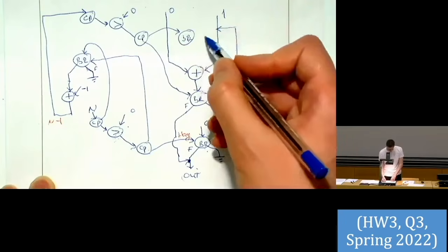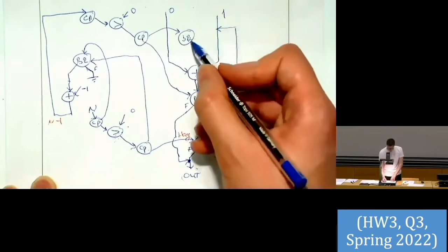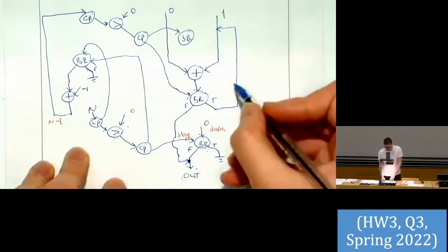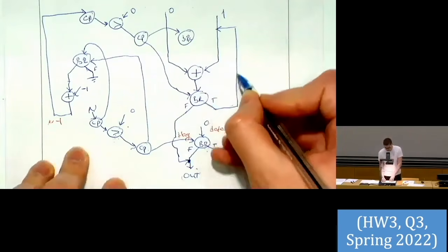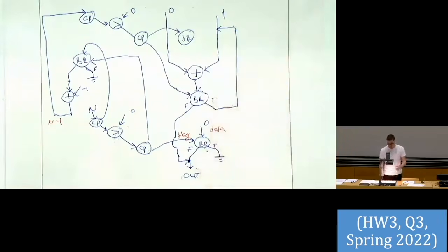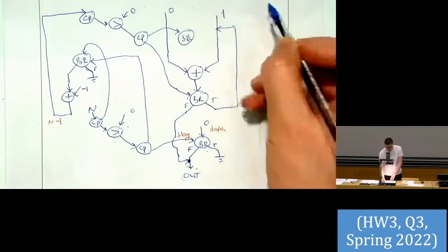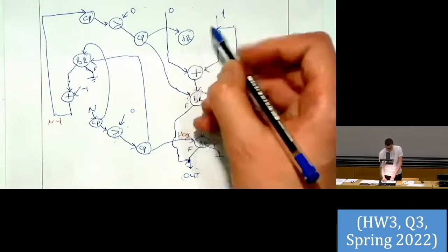But we'll need to forward the same value to this branch logic 2, because this will be the n-2, if you will, right? So this data forwarded here is just the result of the previous iteration, n-1, but we will also need n-2, right? And then we will get it from here.